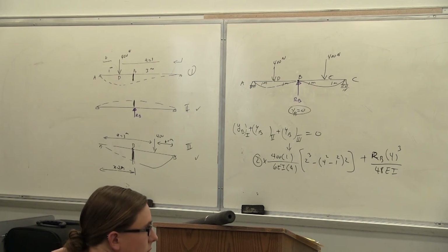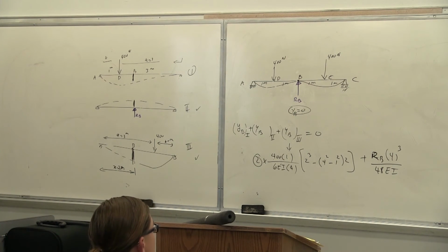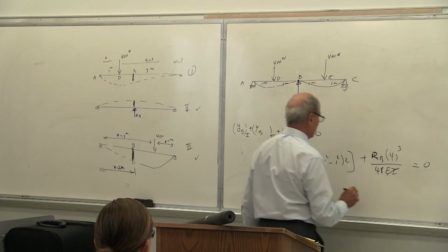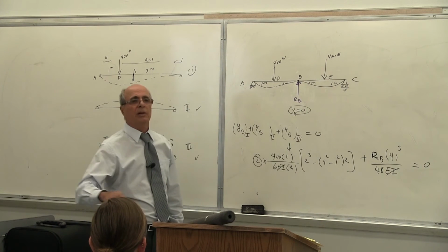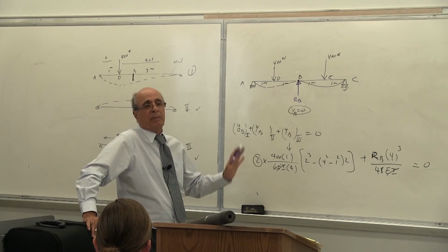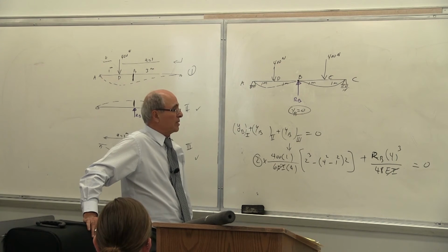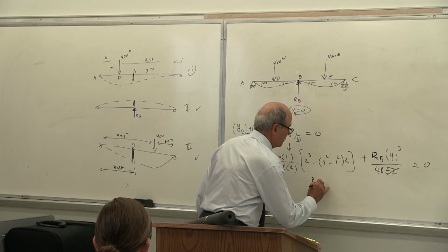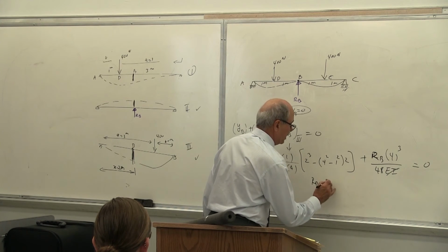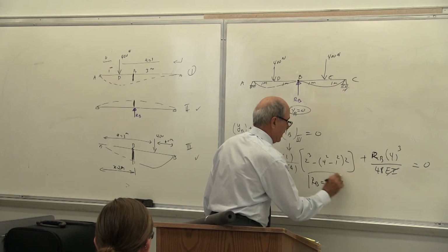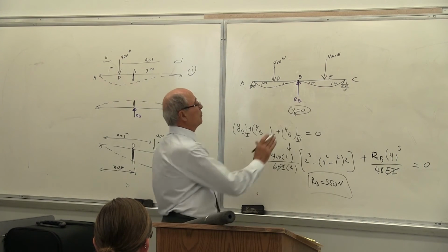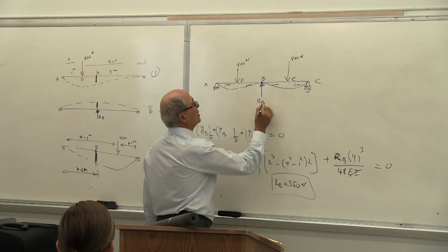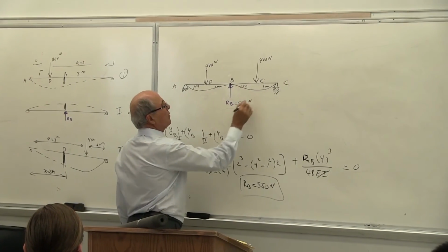Yes? So therefore, you multiply that by 2, that becomes equal to 0, as you see in this, because the static has nothing to do with the EI. EI is going to drop out. Static is never dependent on the EI. EI will drop out there. So use this one equation, one RB. You calculate RB. RB becomes equal to 550 Newton. As soon as you find RB, now this becomes a determinate problem. Look what happened. RB equal to 550 Newton.